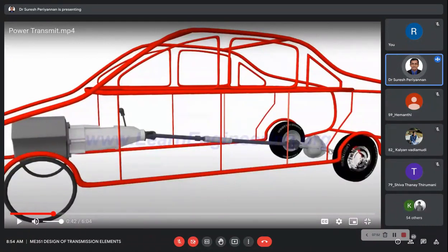So the axle is the outer tube, that is stationary. It's holding the wheel securely and also allows both wheels to rotate. But the axle is going to be subjected to bending moment. For example, consider the load at both corners of the axle.